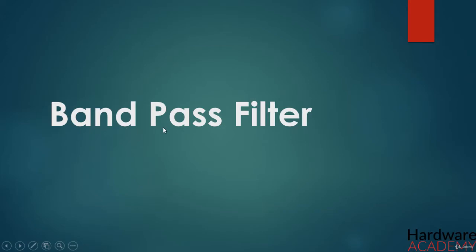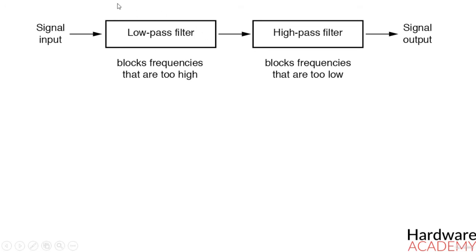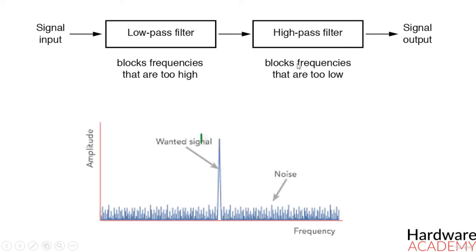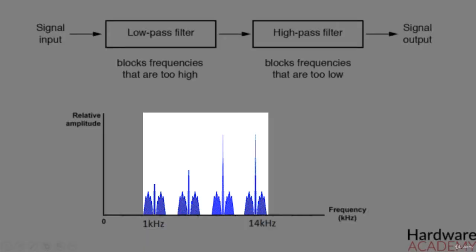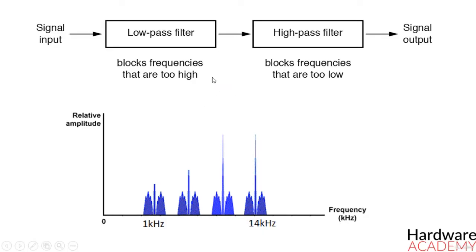used in practical circuits. We can say that a bandpass filter is a combination of both a low-pass filter and a high-pass filter. The name of the filter itself indicates that it allows only a certain band of frequencies and blocks all the remaining frequencies. In audio applications, sometimes it is necessary to pass only a certain range of frequencies. This frequency range does not start at 0 Hz or end at a very high frequency, but these frequencies are within a certain range, either wide or narrow. These bands of frequencies are commonly termed as bandwidth.